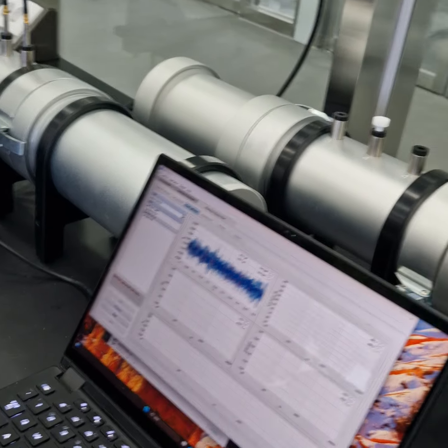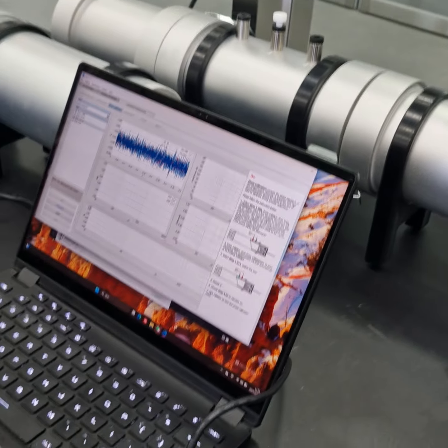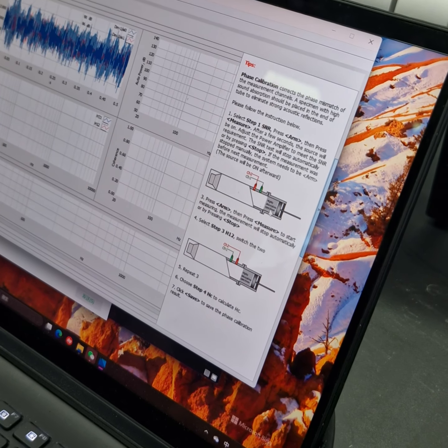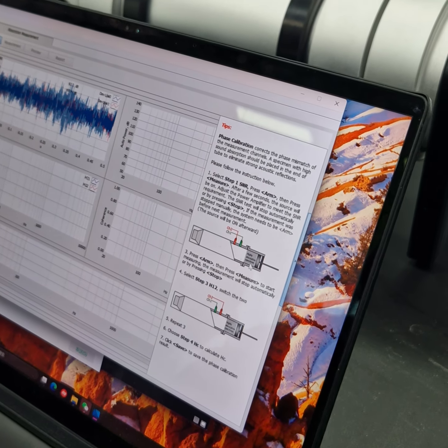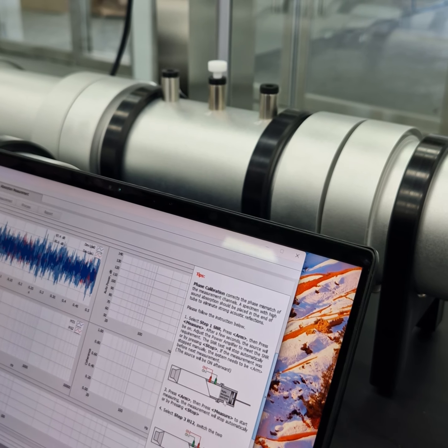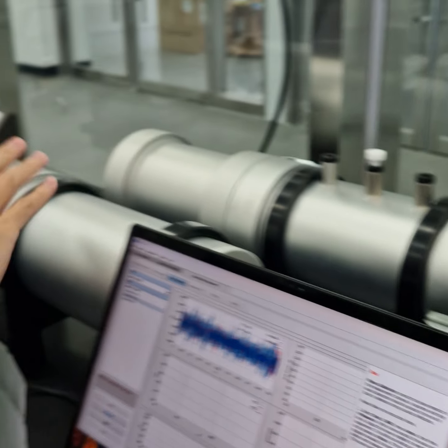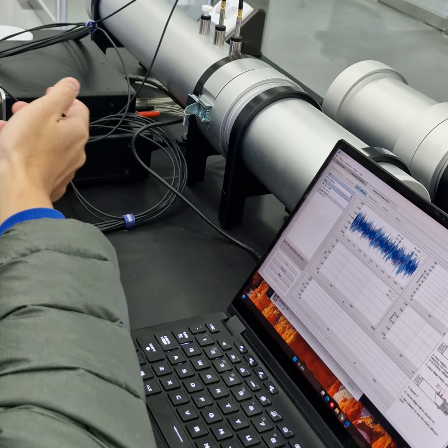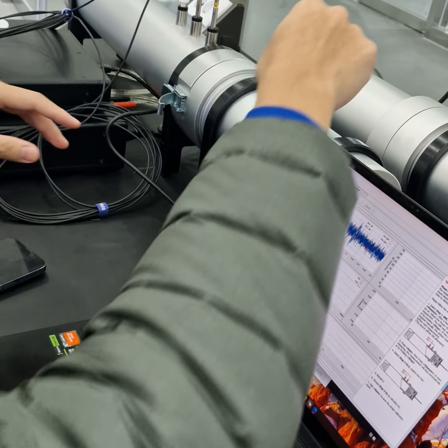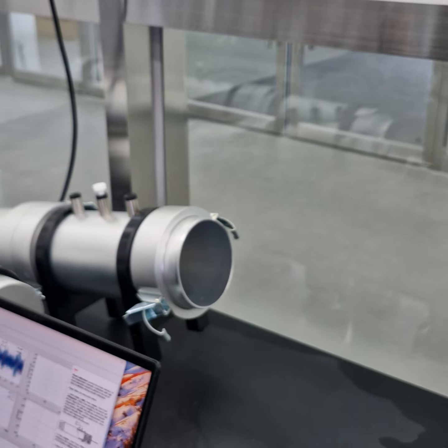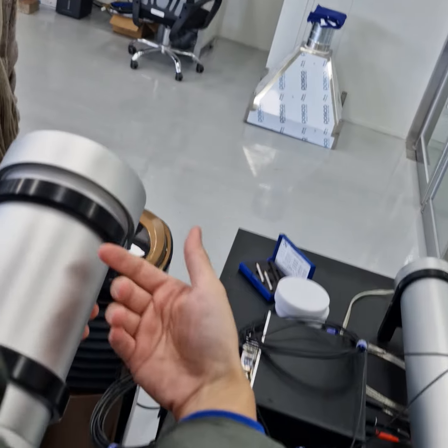As you can see here, in these tips it says highly absorptive specimens, so it needs full absorption in this tube. Sometimes you don't have a very good specimen. The reference sample is a pretty good absorptive material. But if you don't have it at hand, this tube is full of the reference sample, full of melamine.